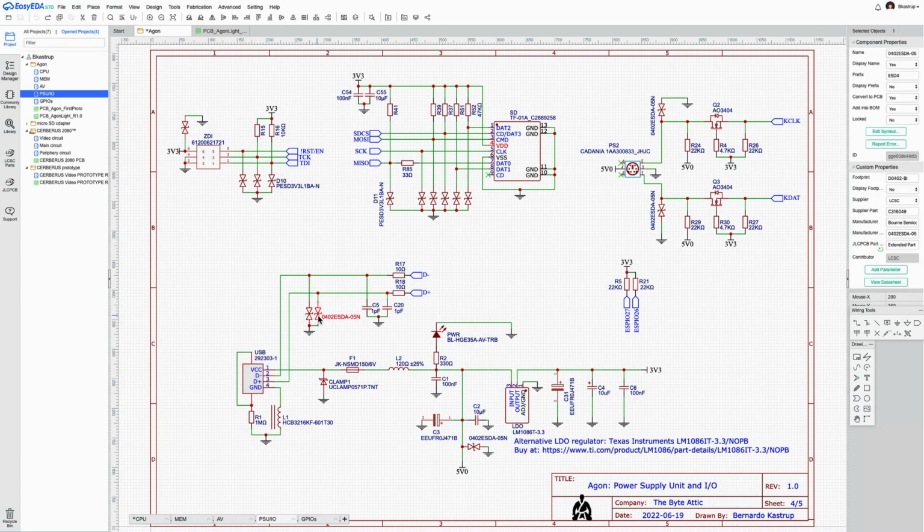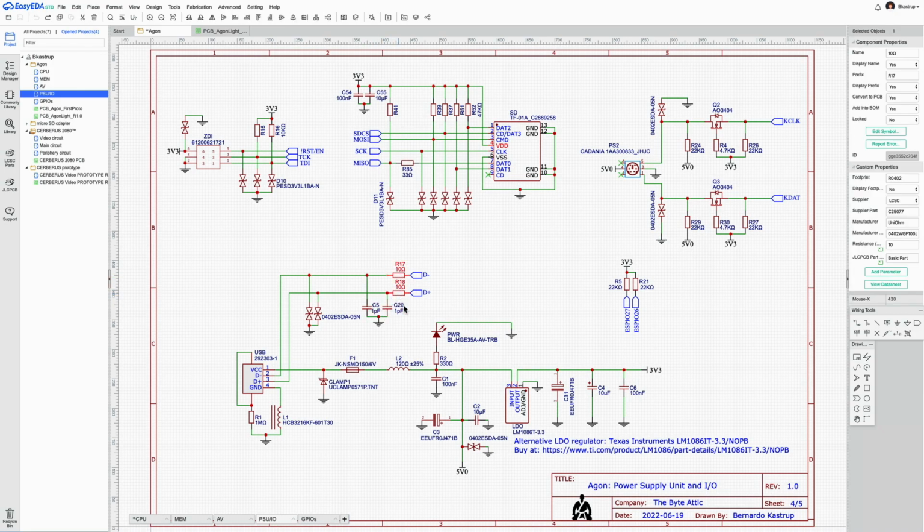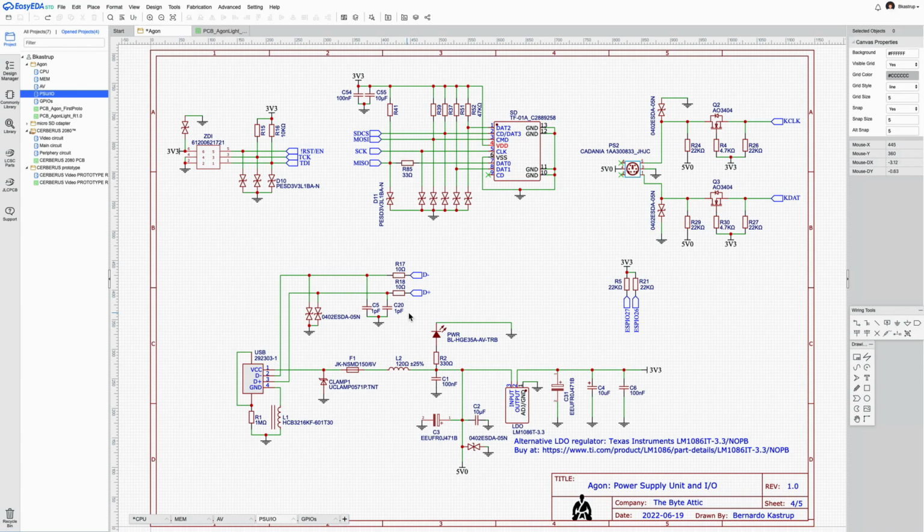They also have the safety diodes here to prevent overvoltage. There is a very, very simple RC filter here with 1 picofarad capacitors and 2 10 ohm resistors, just to filter out some of the noise. And this pair is routed very close together, which acts as an extra sort of common mode filter. And then they go into the USB bridge, which we just saw in the previous slide.